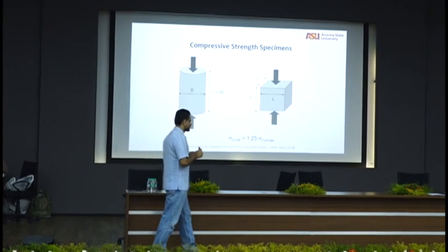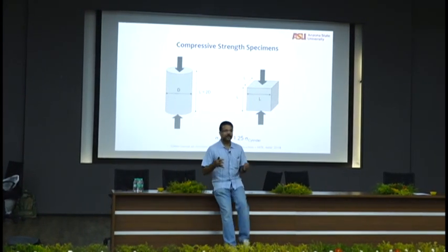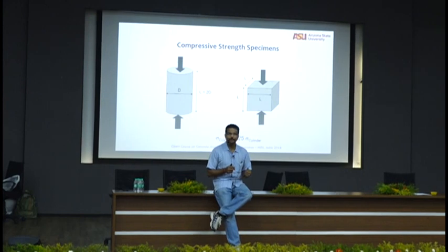okay, I have to take a step back. Is strength a fundamental property of a material? When I say I have a 40 megapascal strength, do I mean that strength is a fundamental material property? What do you mean by a material fundamental property? A fundamental material property is a property that does not change when I test for something in Mangalore or something in Delhi, does not change when I change the shape of what I test, does not change based on the environment and the humidity and the temperature within limits when I test.